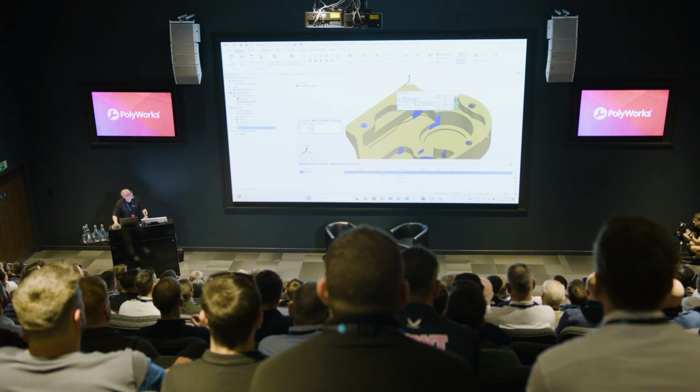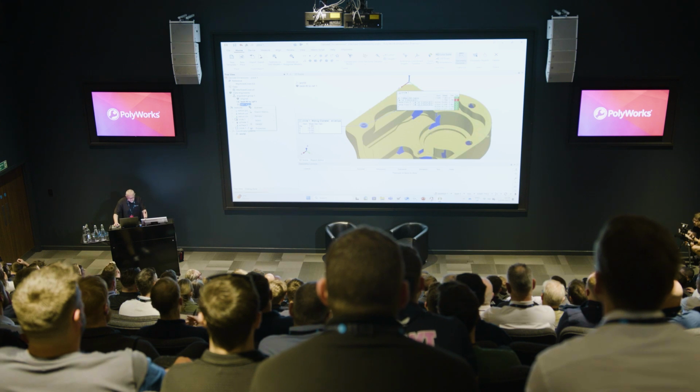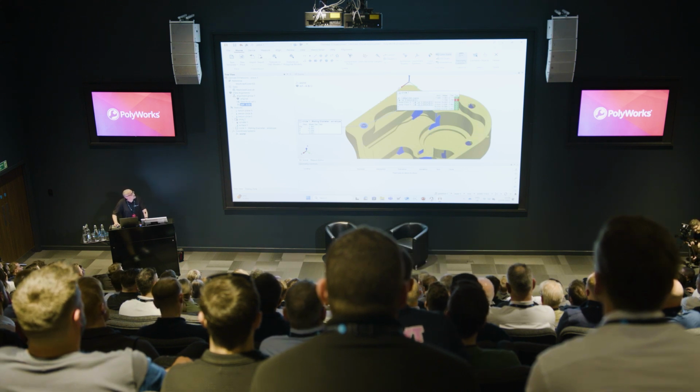Now, we can make these things match. One of the reasons is we're not in the correct coordinate system. So the derived dimensions are always in the datum reference frame alignment. So we need to activate the datum reference frame alignment. And then in the case of the circle, anything that uses the datums is automatically setting the fit type on that. So to make everything match, we'd have to go into the properties of that circle.